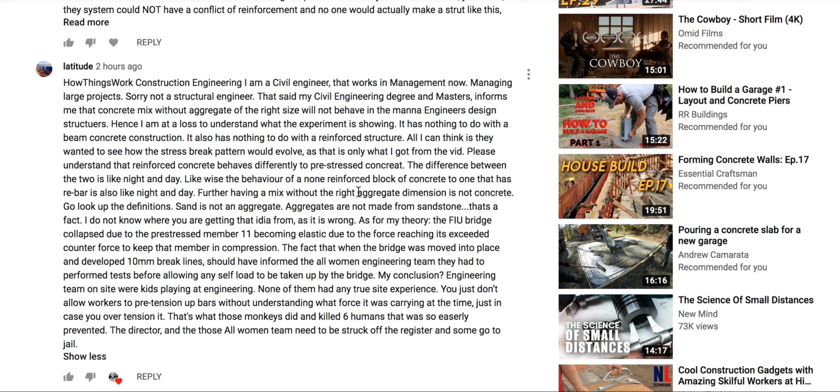Now they use an engineer with some testing and some lab work with this. And they can state that I can give you 3,500 PSI concrete. Now you can't change their mix. You can't say, great, and now I want you to add another bag of Portland to that for me, whatever you have. That's changed the mix design. It's no longer 3,500 plus a bag of concrete per yard. You didn't just make 4,500 concrete. In fact, you might have weakened the design. So you just can't do what you want to do.